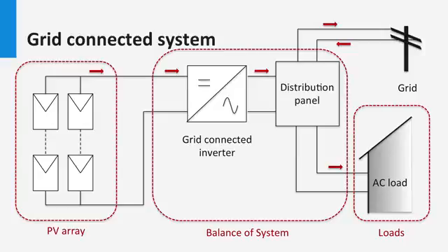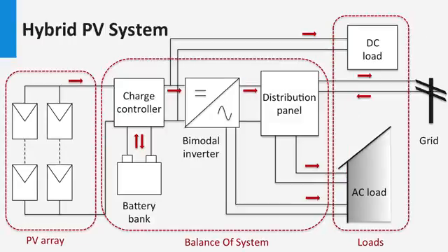The inverter latches on to the grid frequency and voltage. The inverter's main task is to only pump power into the grid. So the inverter supplies AC power to the grid as a current source, while the role of the constant voltage source in the system is fulfilled by the grid.